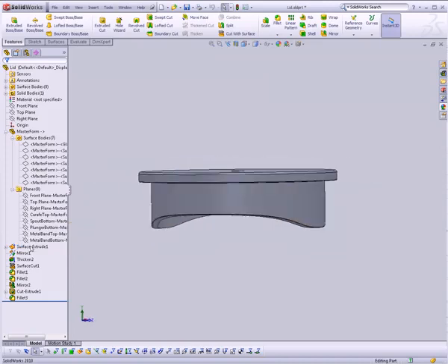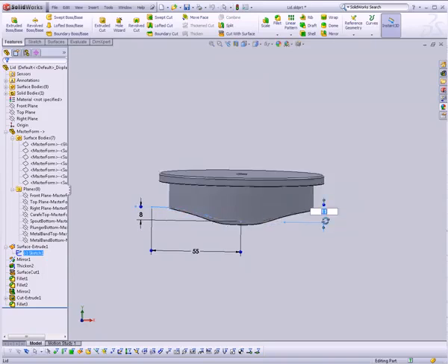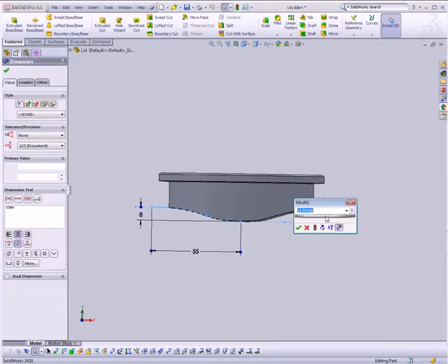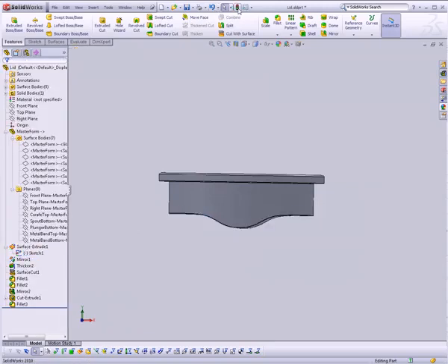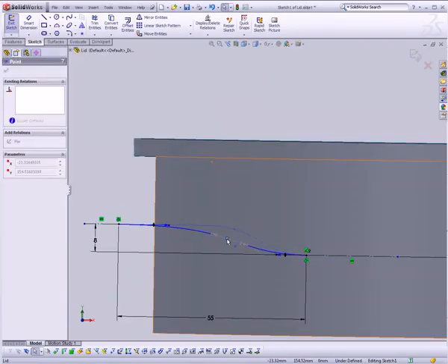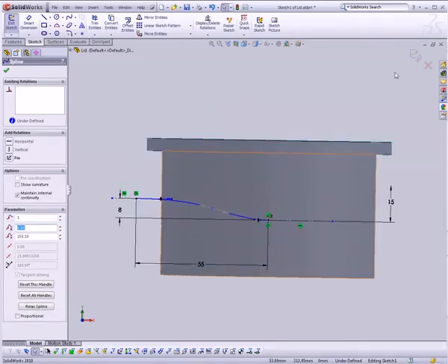Now I'm just going to edit the original sketch for the bottom surface we created. And right now the bottom of it is 11 millimeters from the plane that we have. And so I'm just going to go ahead and change that value. Let's make it 15 millimeters. Hit Update, see what that does for us. Okay, that'll be a little bit better, and now we can just edit the actual sketch to kind of fix that shape, because it got a little bit too sharp there. That should be a little bit better.